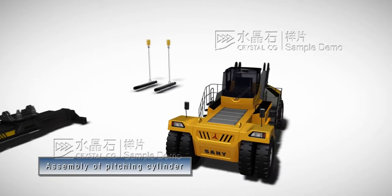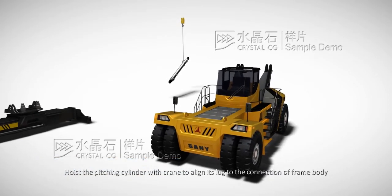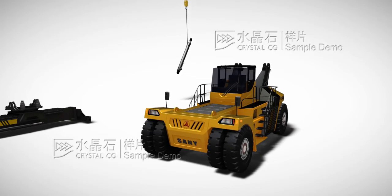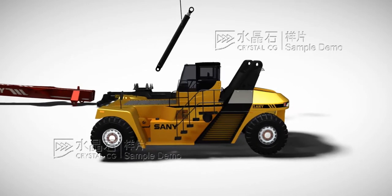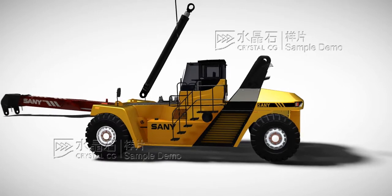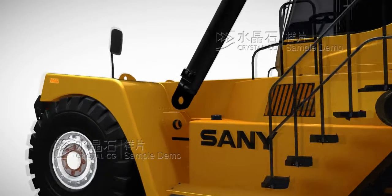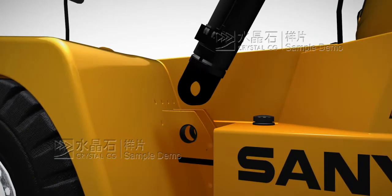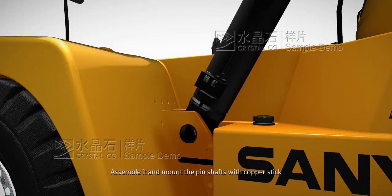Assembly of pitching cylinder. Hoist the pitching cylinder with a crane to align its lug to the connection of the frame body. Assemble it and mount the pin shafts with a copper stick.